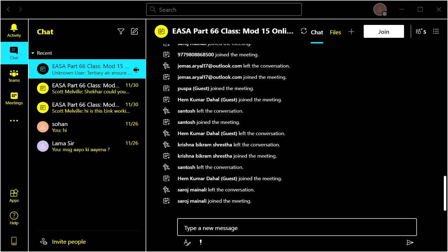The reason they're colour coded, because they will be colour coded for front bearing, rear bearing, intermediate bearing, and so on and so on. So if you get them mixed up, that can give false information to diagnostics and cause a lot of problems. So make sure, take your time, change them one at a time. Okay, and that's a basic magnetic chip detector, or MDP, so magnetic particle detector.